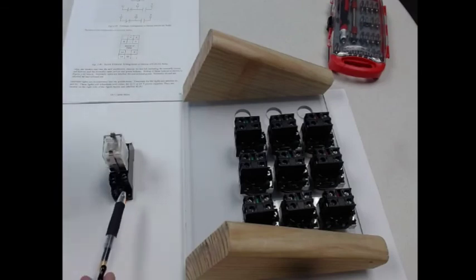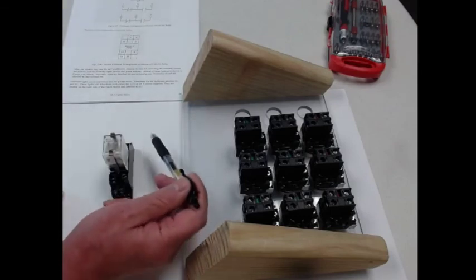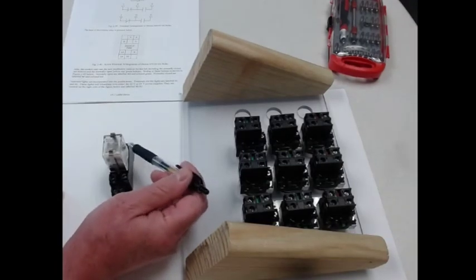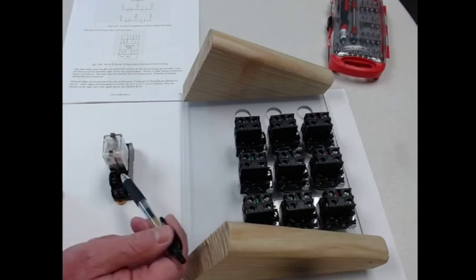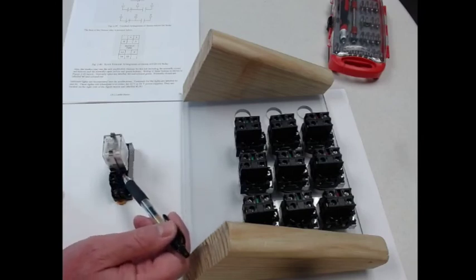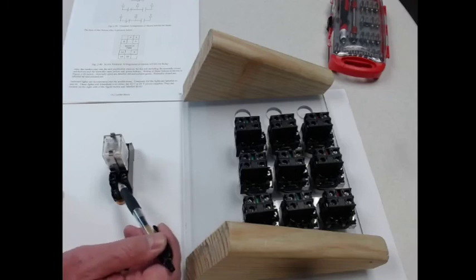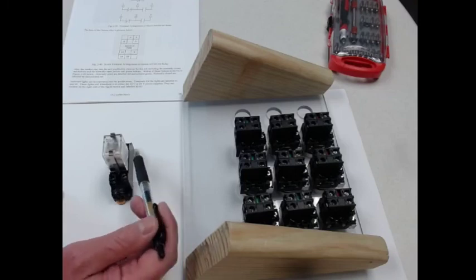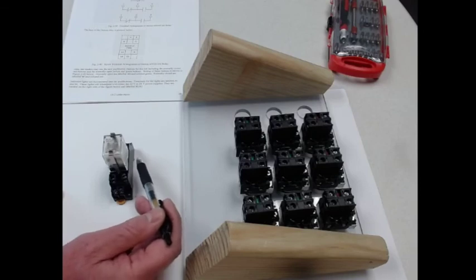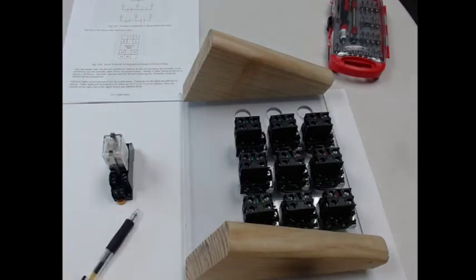We also see a connection between terminal 1, terminal 9, and terminal 5. If we were to take a voltmeter and measure from terminal 1 over here on the left to terminal 5 on the left, we would see it is closed. Without energy, it is closed. We see between 9 and 5 that it is open. Now, in the next minute, I'm going to wire this up, and then we're going to see that this actually changes, that we can actually see the relay moving, and the combination of 1 to 9 will open and 9 to 5 will close.